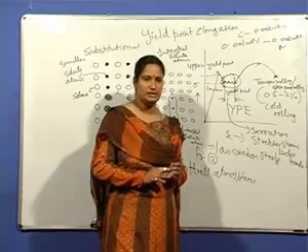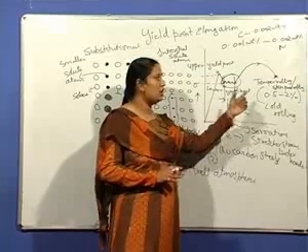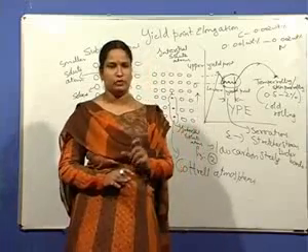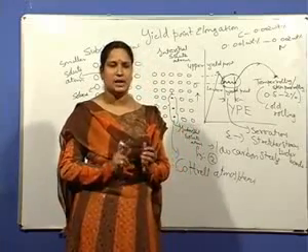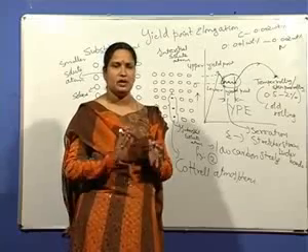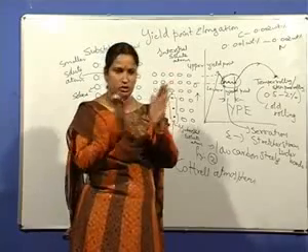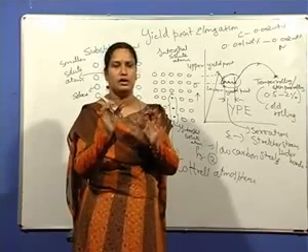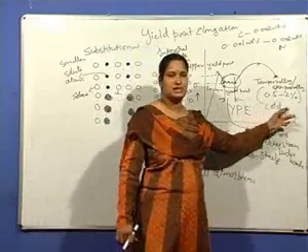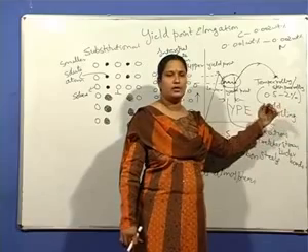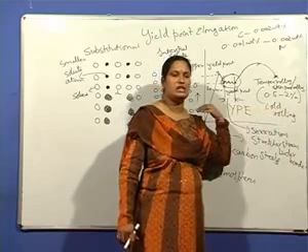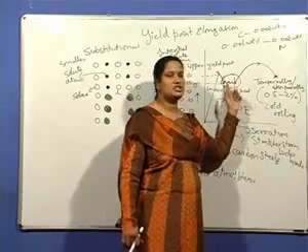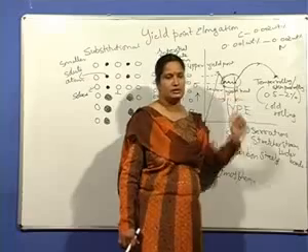In order to eliminate this, a small amount of cold reduction is given by cold rolling. That is also known as temper rolling or skin pass rolling, because the main intention is not to deform the material. The main intention is to give a slight reduction of about 0.5 to 2%, so that more dislocations are formed and they can be easily torn away from the atmospheres, and thereby the yield point elongation will not appear.